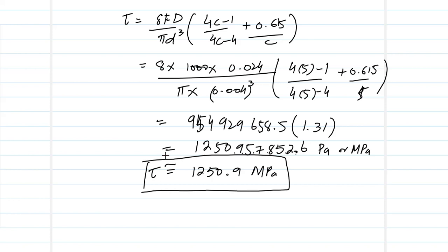Now this certainly indicates that your spring is very small for this much load. Let's say for a load of 1000 Newton, which is approximately 104 kg, a spring of 24 mm diameter is a small spring. Stress actually tells you it's a very high value. So one way of re-evaluating or redesigning the spring is to take a larger spring with a slightly larger diameter, so that the stress induced by the load of, let's say, 1000 Newton is smaller and does not fail the spring.